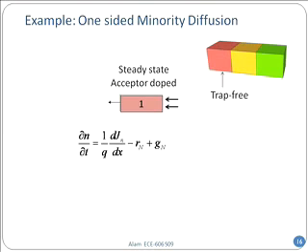Now this time, unfortunately, we'll not be able to take out Jn anymore. First of all, can I take out this recombination and generation? Generation I can take out, right? No light. How come I take out the recombination? Because I said trap free, no traps, no mid-gap levels. Therefore, I can take out the recombination. Okay, that's fine. dn dt, why did I take it out? Because I said steady state. So that's giving you a clue that I want to know in general how the current flows. So that takes out. Electric field is again 0.